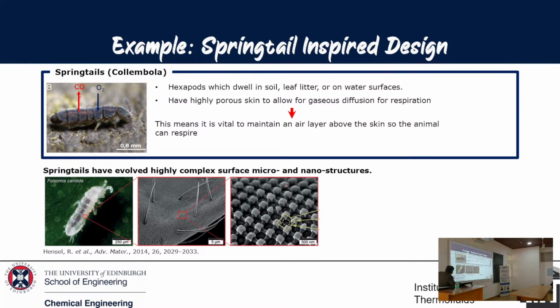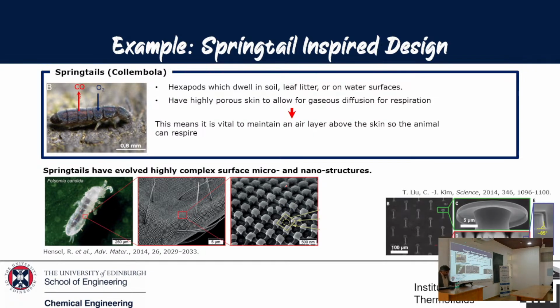So you've got these complex micro and nano structures. You can see that I'm not an experimentalist, I'm struggling to explain all these things. But what you can clearly see when you look at these structures is you've got these pillar-like structures, but then you've got these valleys, and these valleys are the ones where you need to take a lot of care, because if you want to make sure that it's hydrophobic, you need to encourage a Cassie-Baxter state. You should discourage a Wenzel state, so that you don't get trapping of liquid, and that's a major challenge.